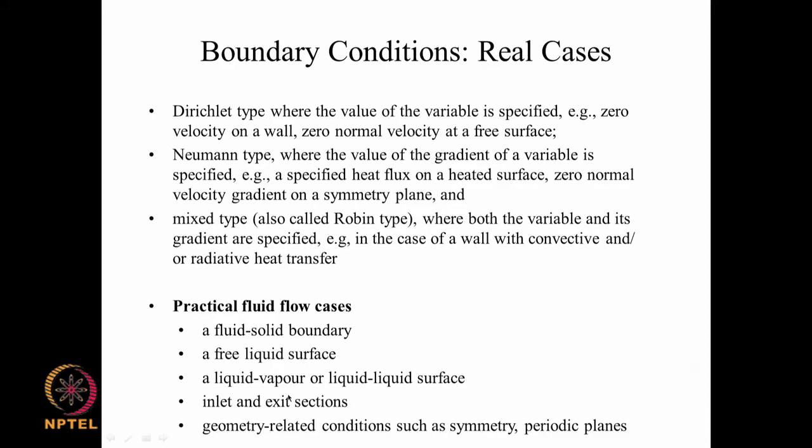Or in the case of free surface flows, free liquid surface, we can bring in the surface tension and we can bring in kinematic boundary conditions, dynamic boundary conditions, which take into account the curvature of the interface. And you can have a liquid vapor or a liquid liquid interface, and across this liquid liquid interface you can actually have mass transfer, whereas typically across a fluid solid boundary we do not have mass transfer. So that is an impermeable wall boundary condition, except in certain special cases where we can specify, for example, a blowing boundary or a suction type of boundary. That kind of thing is also sometimes brought in here.